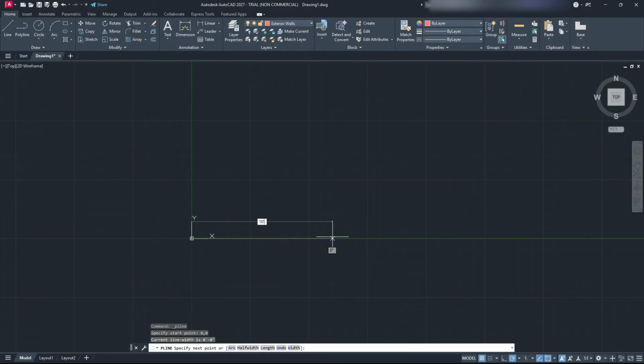So we're going to do 10 feet. And once we're done that, we can lock that in. We press tab again, and then you can see we can actually adjust the angle. This angle is going to be relative to where you are. I don't know where mine is right now, but you can see here I can lock it in. It's locked in at 10 feet, and I can change the angle by going up and down. If I go up 45 degrees, that's what my line is going to look like. If I go up 90 degrees, it's going to look like that. I want to stay here at 0, so it's already at 0. So I'm just going to press enter, and that is going to be my first wall.